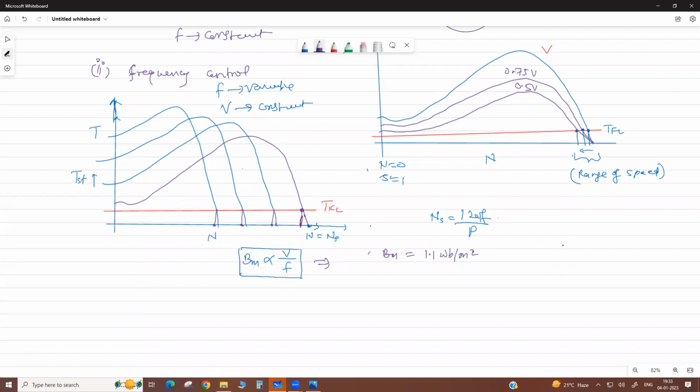Accordingly, the size of the motor is decided. It means the dimensions, like core dimension and yoke dimension, the length and diameter of your motor yoke. These are the two parameters. So it designs the iron part also: how much iron core, the volume of iron.